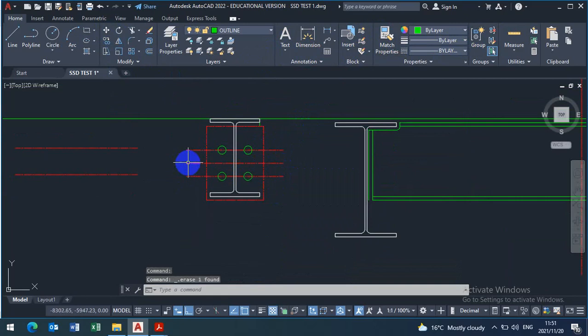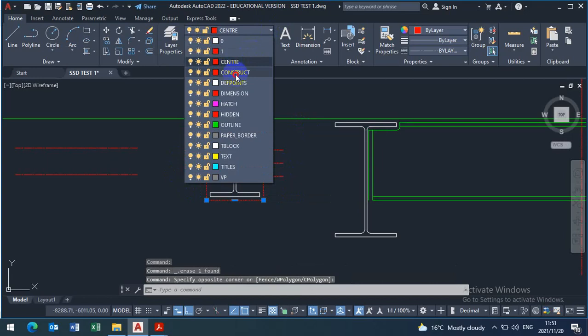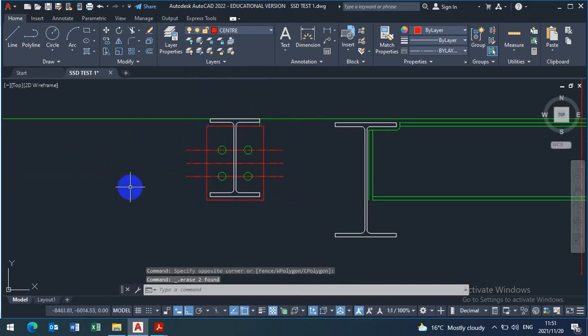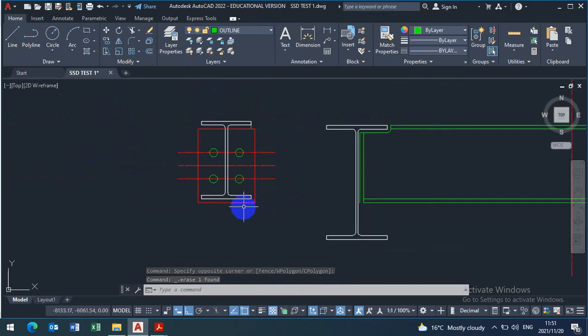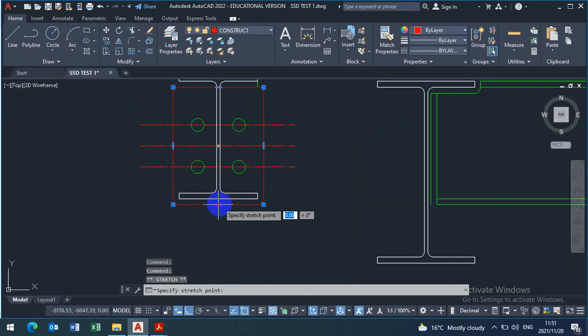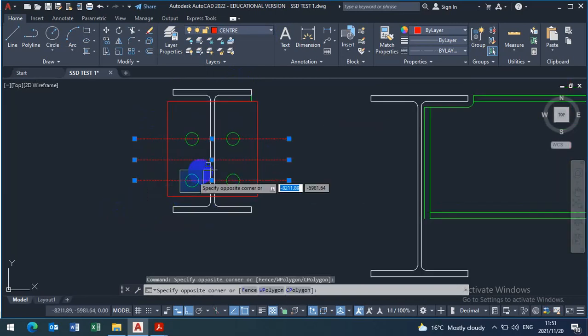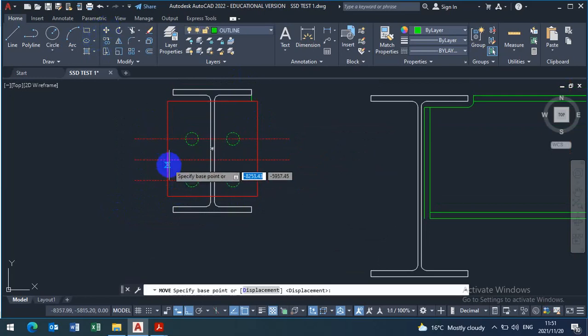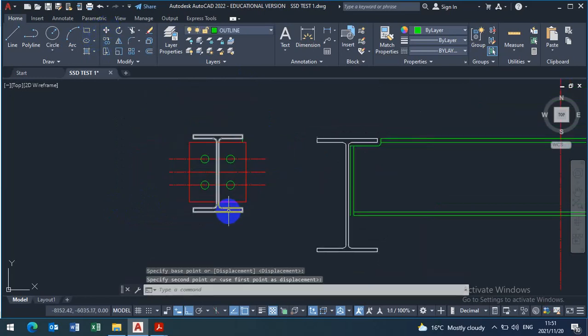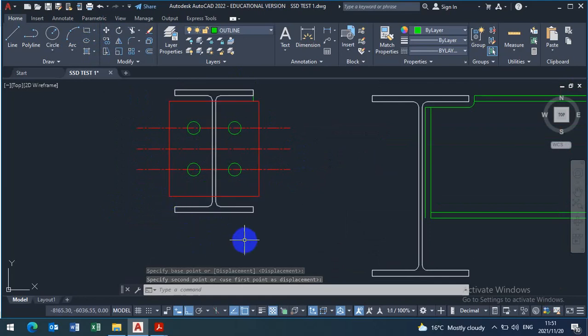You can delete this one and then change this plate to construction line. Delete that, delete that. So if you want to save money, what we usually do is this one won't even go up until there. You can go inside by 10. The same way this one was sitting, you can come down by 10 and by 10, and then you weld it there. And then once you weld, you're going to move everything here, the center to the center here. Then you save money than you welding everything up until the bottom.